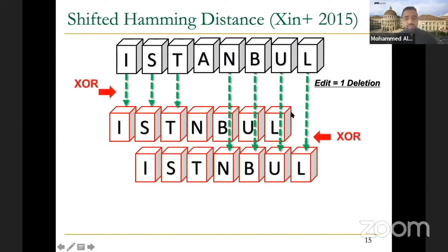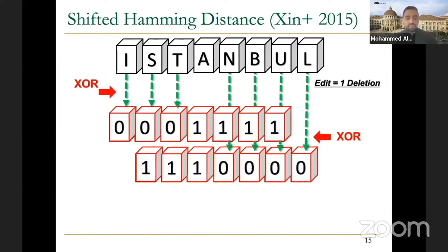So we have 3 here and we have 4 there. How can we do this in an algorithm or in hardware? The match operation we can do directly using XOR, right? And now these are the XOR results. If you convert the match into 0, because there is no difference. In the XOR operation, if the number of differences is odd, then you always get 1, right? But since here they are always the same character, T and T, that is even, not odd. That's why you got the 0 over there. Now, what is the heuristic or the right operation to be used so that we can combine the zeros from there with the zeros from the second version?